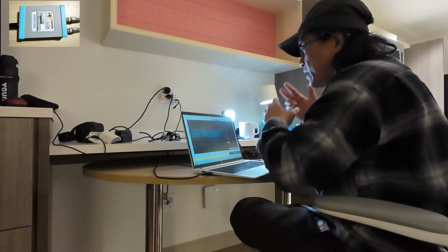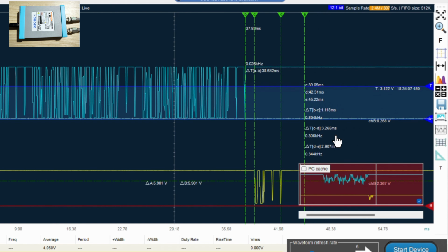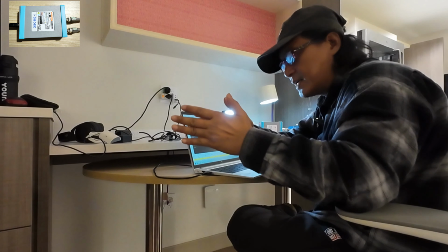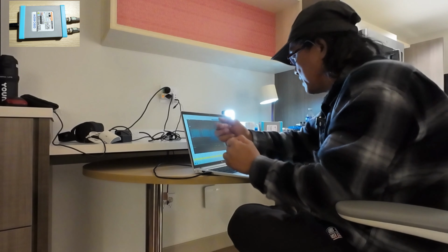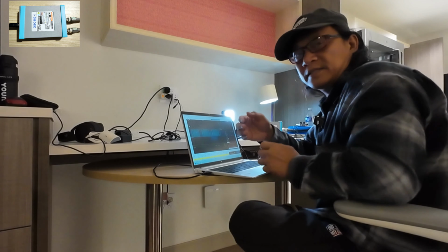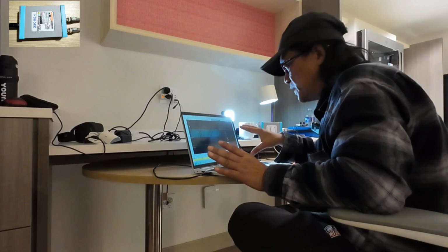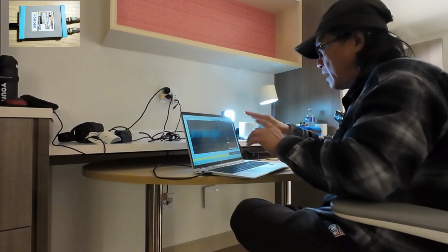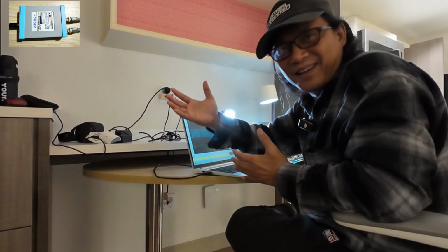Now, with the OSC482 oscilloscope, I am able to explain what is really happening in the TX blinking. You can see it's a series of on and off, very fast, and how long the TX LED takes to blink, as well as the interval between the TX and the RX LED. And also I can see the RX LED characteristic in its waveform. That's a pretty easy demonstration of how I can do a deep dive on simply an LED.